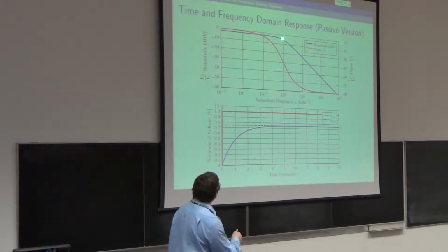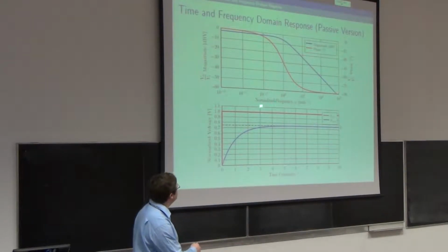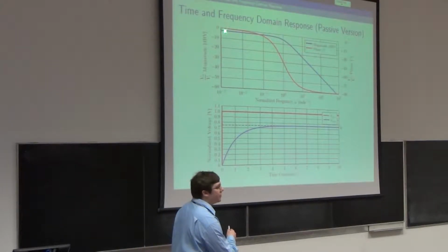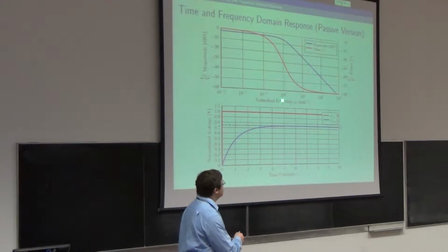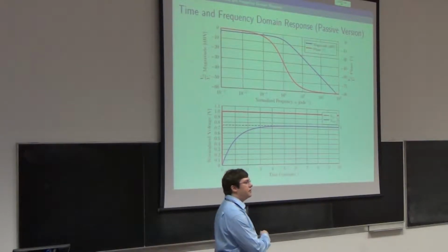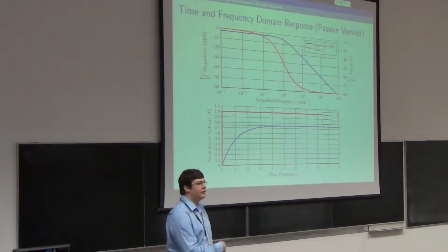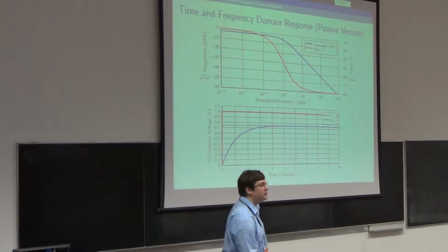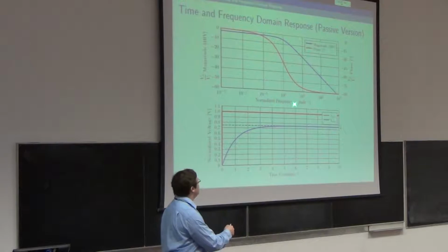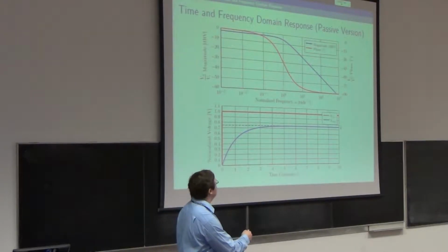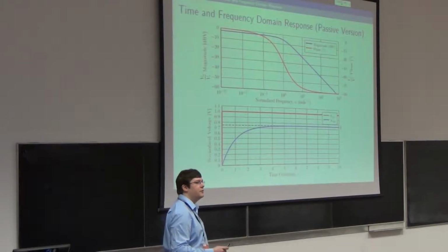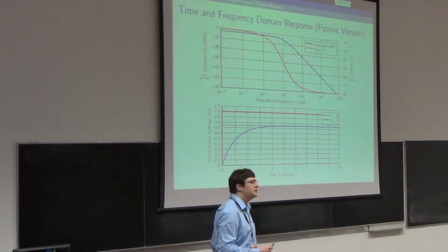And there is a corner frequency, and I've done this normalised frequency business. So I've called this corner frequency, which is 3 dB down on whatever K was, 10 to the 0, which is 1 radians per second. Now I didn't actually design the filter at 1 radian per second, or maybe I did, doesn't matter. I've scaled the axes to make it so that you can see if I go 1 decade, 2 decades, 3 decades away, how many dB reduction I get. And it doesn't matter about the exact numbers. Happy with the idea of normalising the frequency axis? Yeah?